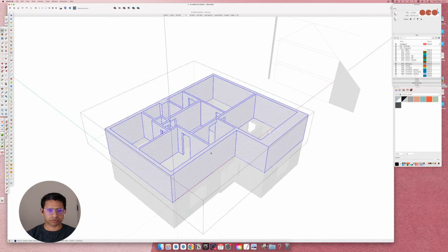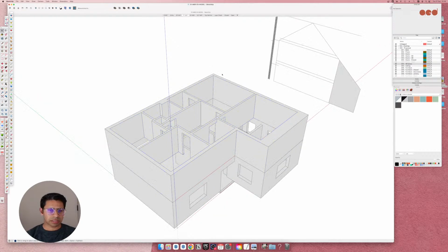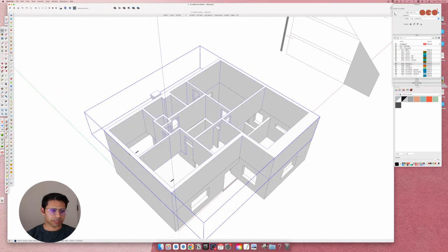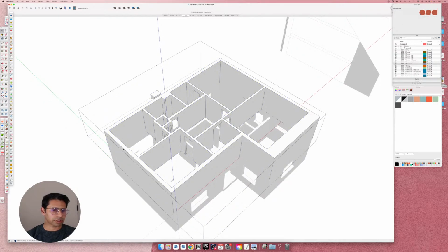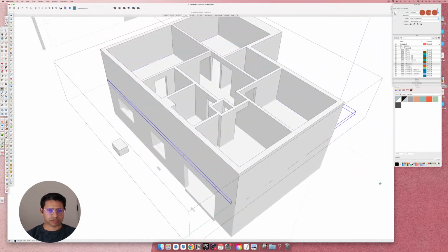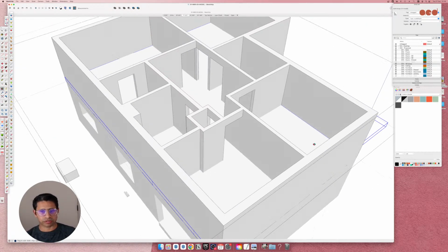So I'm now into the first floor group. Let me just group these walls and put them on the right layer, and then I go edit, and need to be inside. So if I click on that, you'll see that I modeled this onto 602 first floor layer. So double click into that and say edit, paste. Now what that did was take the floor plate and paste that into the first floor model.